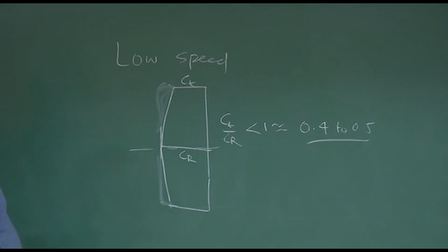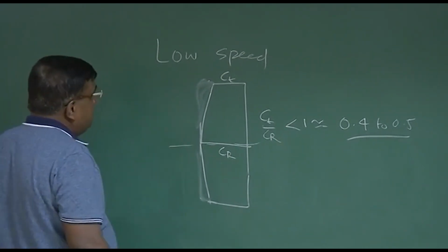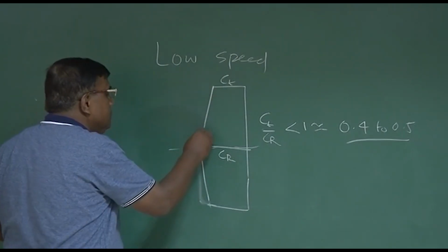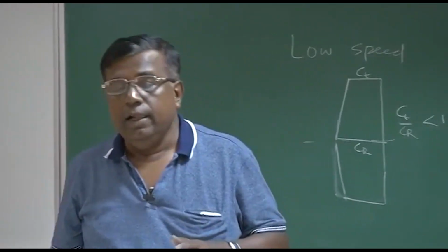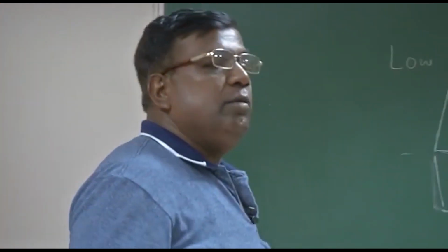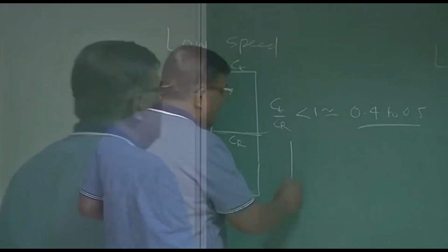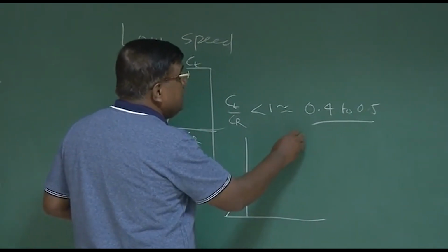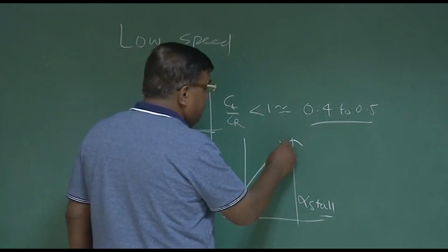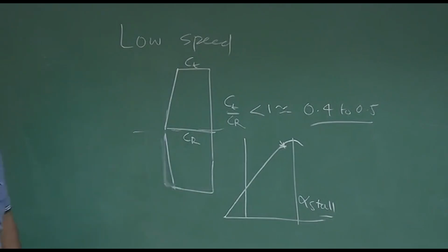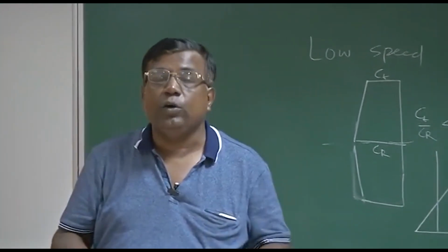Also, very important, please understand this. One of the major challenges for flying is the natural tendency to fly at a higher angle of attack, if possible, at a lower speed, so that the engine power requirement is less, and you get a lot of lift from the interaction with the medium. As we try to fly at a higher angle of attack, there is a danger: I should not cross alpha stall. Also, suppose I am flying here, although I am not in alpha stall, because of some upward gust, the local angle of attack may change and the airplane may go into a stall.